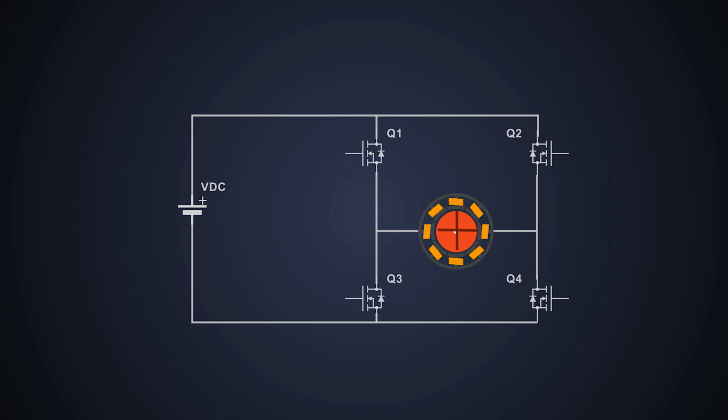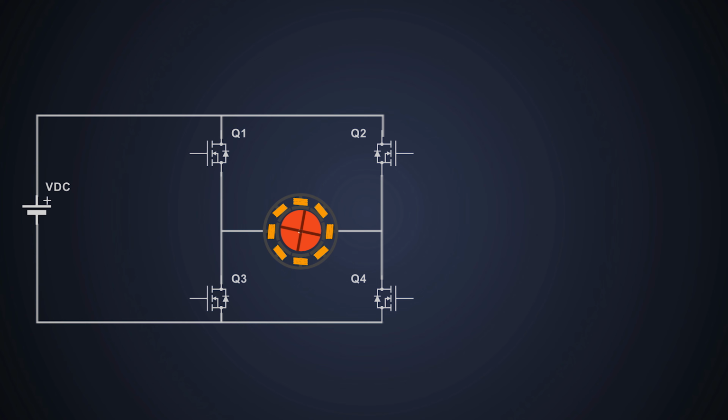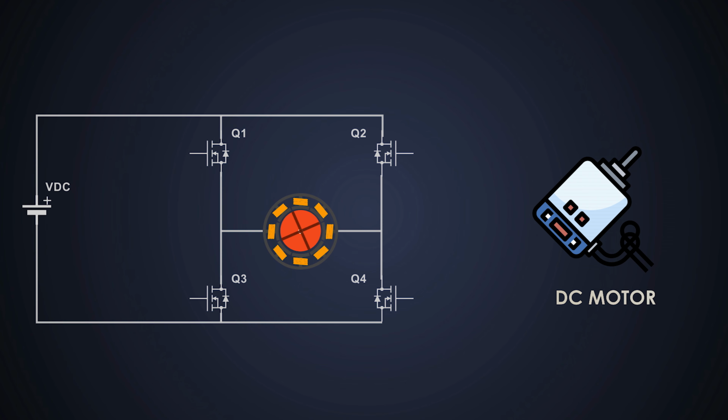The H-bridge, also known as a full bridge, is a switching network consisting of 4 control switches, which are MOSFETs, and is capable of creating a bidirectional current and reversible voltage across the load. The load is nothing but a DC motor. This circuit drives the motor. Well, we can even change the speed of the motor with this. It comes in handy while driving a motor because it allows a change in the direction of its rotation.